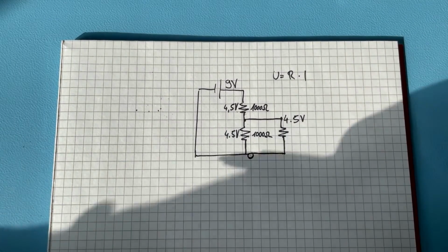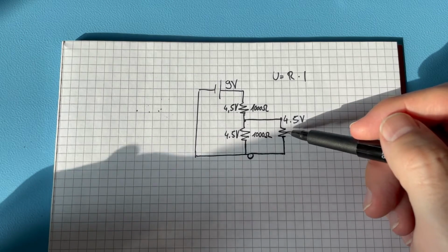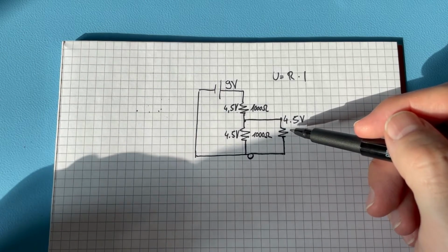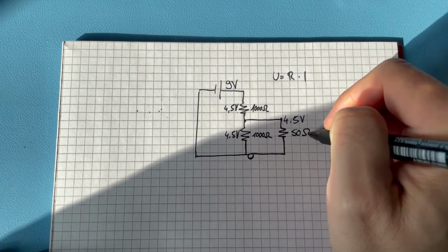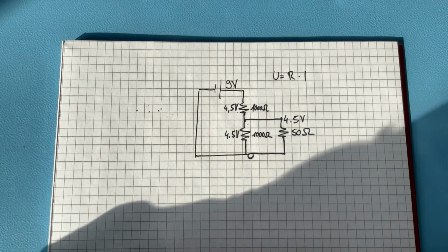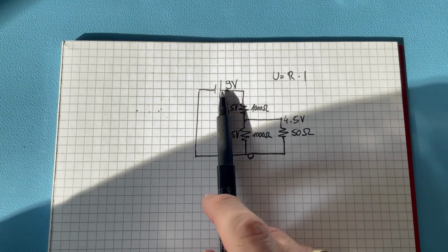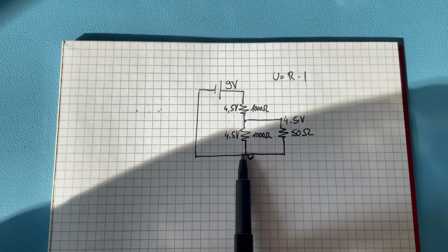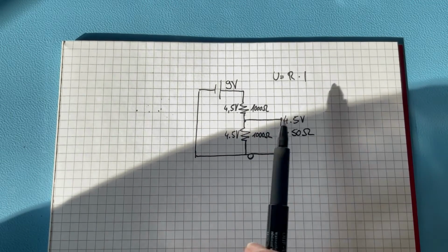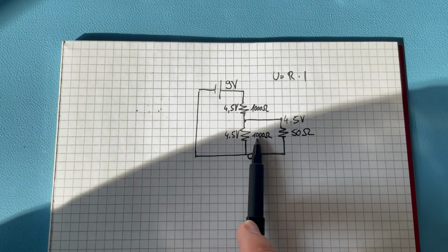But now the thing is, let's look at the situation. Let's say this load has a resistance of, let's say, 50 ohm. That is quite common. Okay, but is the situation then the same as we had before, where the same current was flowing through the same resistors, when we have this 50 ohm here in parallel to this 1000 ohm resistor?